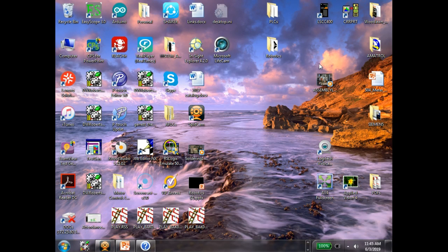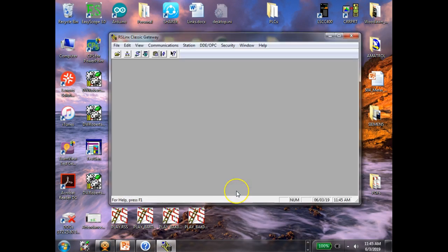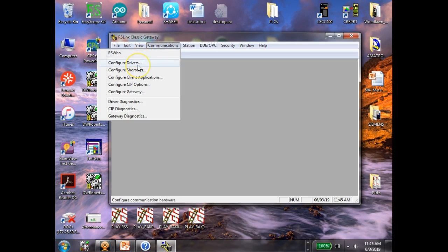So we've got all different types of communication that we can hook up with this PLC right now. So before I can communicate with this thing, I've got to make sure I have what installed? Driver. So to install the driver for your PLC, Allen-Bradley uses something called RSLinx, and this comes with the package that you install. And this is even on RSLogix 5000, which is the new version. So the first thing you're going to have to do is establish a connection to the PLC.